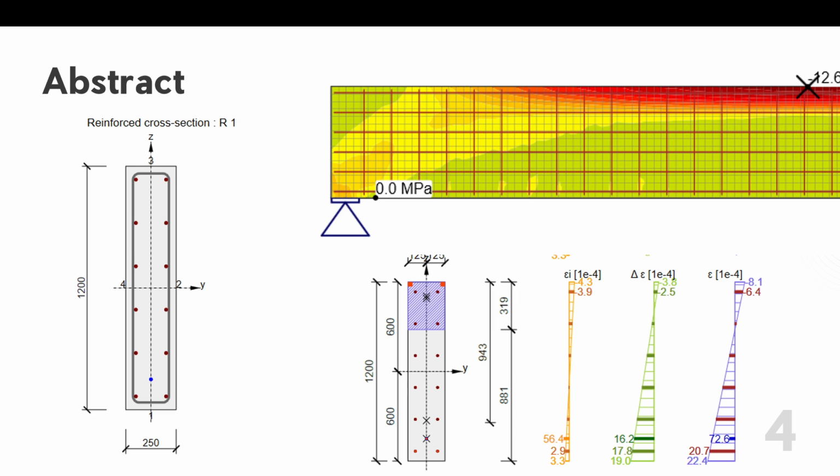The reason will be the tension stiffening that is applied on the reinforcement rebars in IDEA StatiCa 2D detail, and it leads to a different plane of strain, and the neutral axis is shifted. You will be able to observe why the stress level in the reinforcement is different.